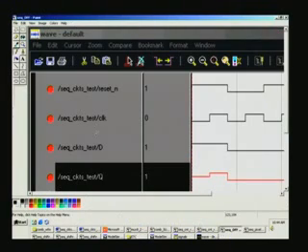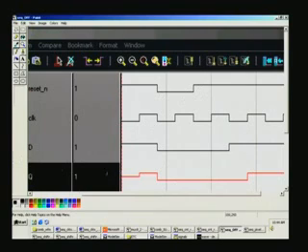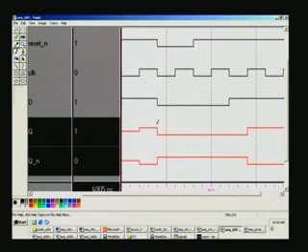It's here. So here we have reset N, clock, D input and Q. It's quite simple for you to find out. Whenever you reset, Q and Q bar, right? The moment you reset here, Q is cleared. It was 1 here, so it is cleared now, and Q underscore N is made high, Q bar basically. Subsequent to the reset being on, after a small duration, this is the power-on reset we can consider here, and after that it has got to be high in the normal working state.